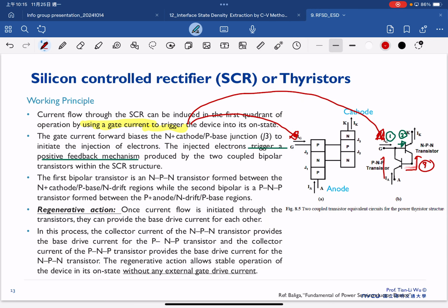So once this turns on, this becomes another contribution here. And then this becomes a loop. Why does it become a loop? Because this current is supplied again into the base of this ampere. So now you can foresee this is kind of like a closed loop that generates the current by itself and then cannot be stopped, because there's no way unless you do something additional.